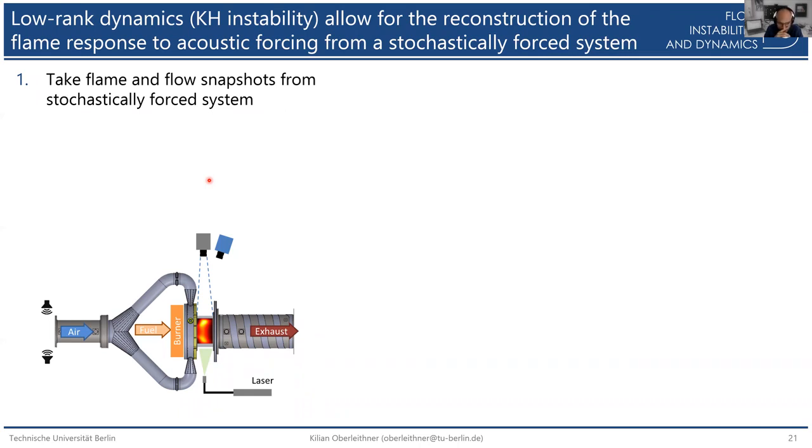And experiments are very difficult to do in this configuration. We took some OH chemiluminescence data and some PIV data in such a combustor, and then we do a data-driven reconstruction of our response. So this is relatively straightforward.